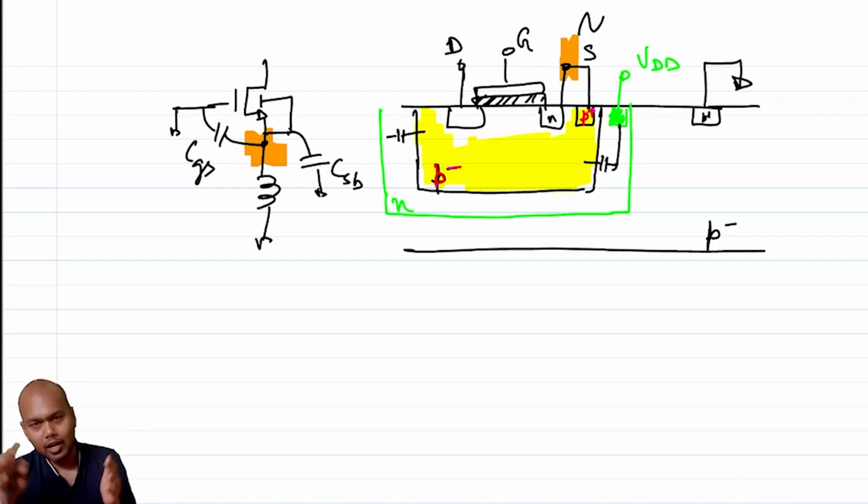But if you take a 100 gigahertz FT transistor and you want to work at 20 gigahertz, or even 10 gigahertz, you really have to start bothering about these effects. In those cases, if because of the choice of these architectures your 100 gigahertz FT transistor goes to 80 gigahertz, then it's a serious impact.